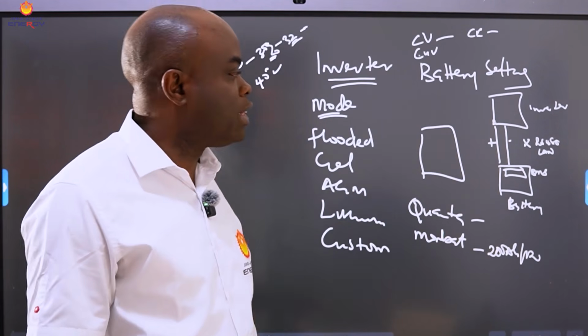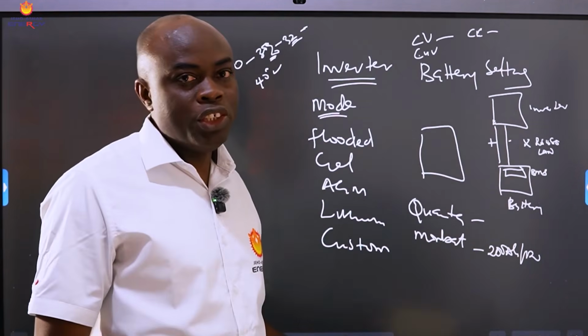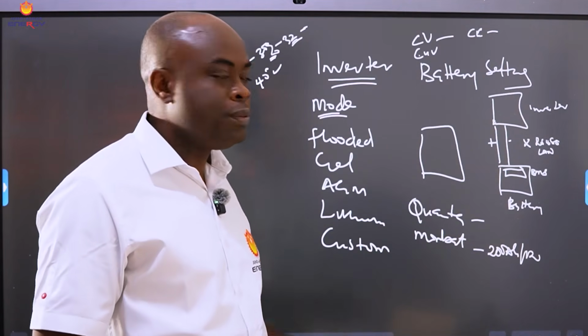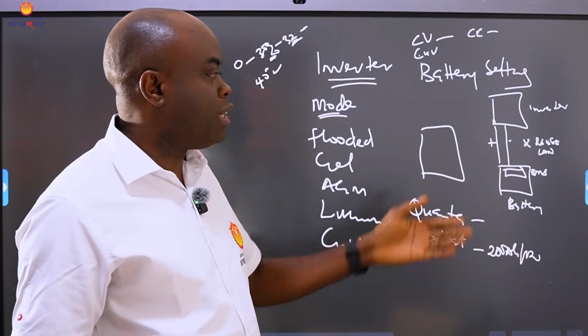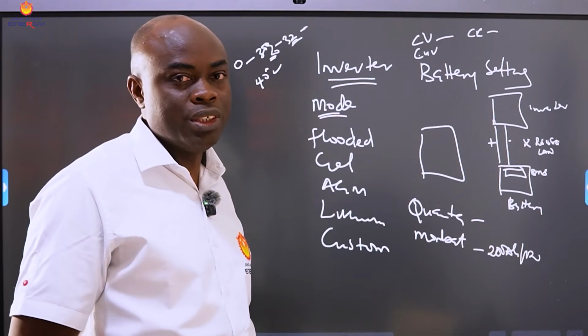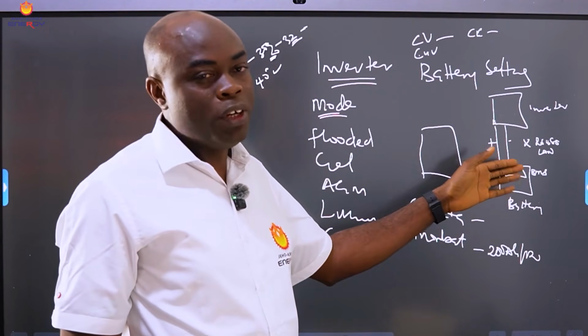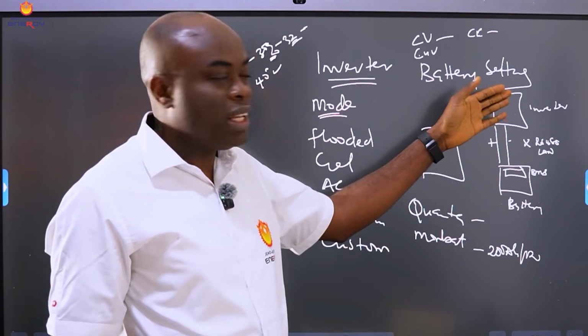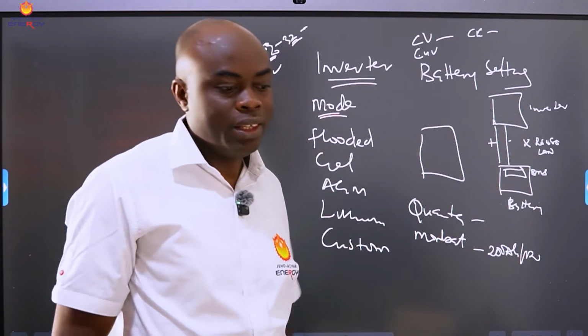Because if you don't have this connected, at the end of the day, your battery... maybe we are in Nigeria, a hot region, you place your battery outdoor, and probably you don't give it good ventilation, you don't put an air conditioner in the storage unit, and this man keeps charging this battery. The temperature of the battery is high, but the inverter doesn't know because there's no communication between it and the